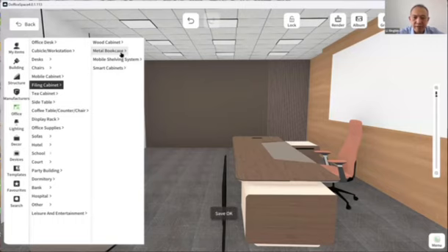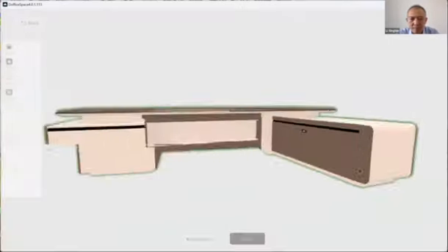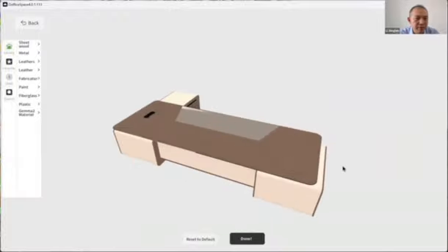Alternatively, if you just have AutoCAD, then convert that into white furniture without any material or texture, and then upload that as a furniture model to the backend system. You will see that as a white model, and by doing this material modification, you will be able to add stuff on top to change it to your own color.